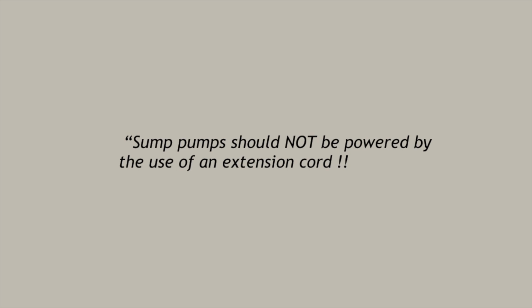A controversial issue among industry professionals is, do you write a defect if the sump is not connected to a GFCI outlet? There is an argument for either situation. Some say the pump needs to be connected because of an electrical outlet and water is in close proximity. Others say if the GFCI is triggered, the pump won't work and the basement might fill up with water. I suggest you note if the pump has a GFCI or if it doesn't have a GFCI and not make a concern out of it. If you make a concern out of it, then in effect, you are offering engineering advice.